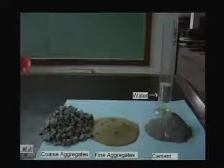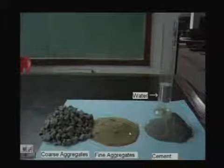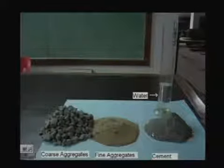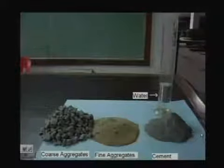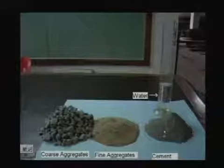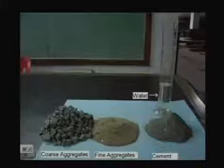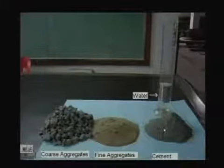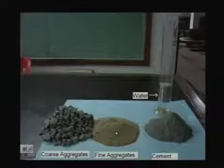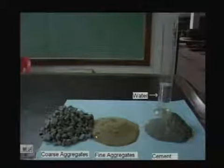Please note this, because whenever we talk about reinforced concrete, we should remember these different parts. Generally the ratio comes as 1:2:4. If we consider 1:2:4, the ratio of cement, sand and coarse aggregates, then 1 means cement, 2 means sand, and 4 means coarse aggregates. We generally do not specify the water. We also have 1:1.5:3. These are generally guiding ratios, and we call them nominal mix.